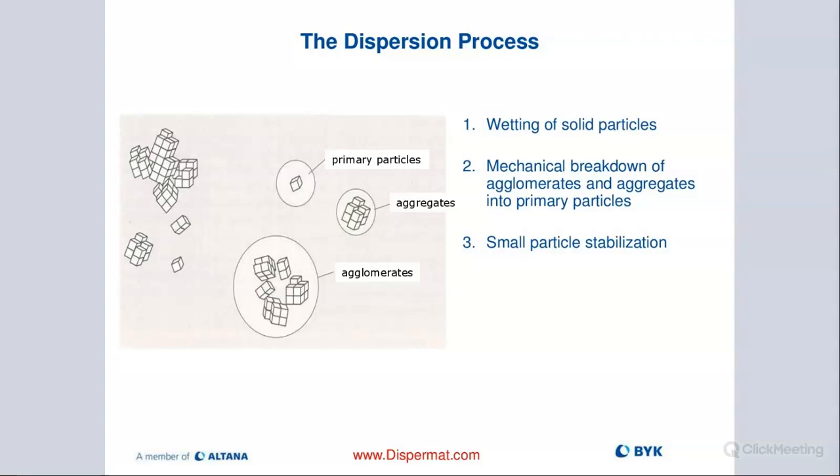And then when we take a Cowles blade and we expose these agglomerates to our Cowles blade at a high tip speed, between 18 to 25 meters per second, which is an optimum pre-dispersion tip speed, that will allow us to pull in enough shear to break up the binding forces and reduce these agglomerates to smaller particle clusters we call aggregates.